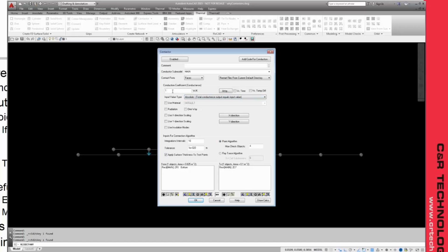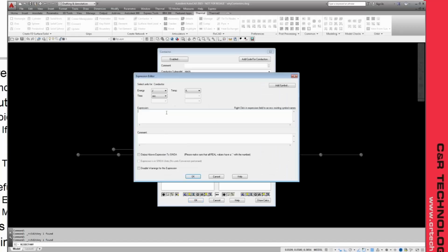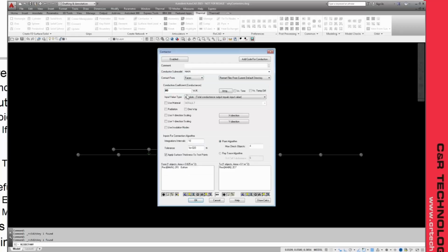And then probably the easiest thing to do is go ahead and double click in this field. And I would say it's 5 per bolt. And then I have 8 bolts that are holding this down. And when I say OK, that comes back with 40, which is my total, and that will be distributed over the entire connection.